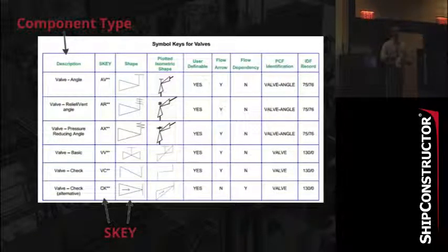Flanges and branch types. Again, there's so many options with these things, and the list that we can put these things into is ridiculous. This is 1/3 of one page of a 96-page document that has all of the available types within the PCF file. So us being able to map that into our catalog, there were a lot of things that we just couldn't decide, but that would be based on how you guys are setting up your catalogs. It should be pretty quick for you guys to go in and map those things, and once you set it up, you're done. It's all stored in the database and kept there for you automatically, and we've made our best guesses in the cases of the manual setup ones to try and get you started, but fundamentally you still have to set up a component type and an S key.